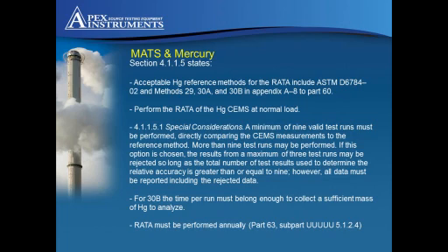RATAs must be performed annually with similar sorbent material as the reporting system is using, which in theory means using the same or similar type traps. Typically, traps used on a 30B RATA are 2-bed traps and are cheaper than 3-bed PS12B traps that you'll be using for everyday monitoring. Finally, this RATA must be performed on an annual basis, as I said before. There is a little more to this, though, than just that simple statement. So let's take a look at what that actually might mean.